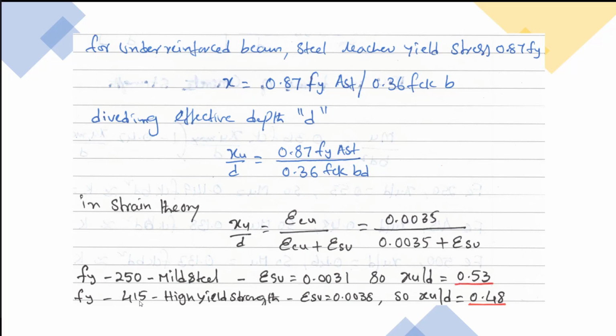However, over-reinforced sections normally lead to the concrete failing first, and that will be a sudden failure, which causes more damage compared to under-reinforced sections. So one should avoid over-reinforced sections, and in practice we mostly don't allow the design of over-reinforced sections.